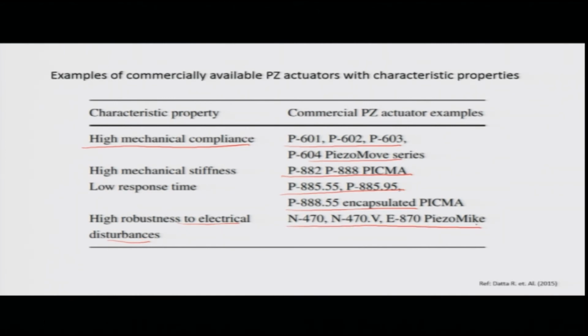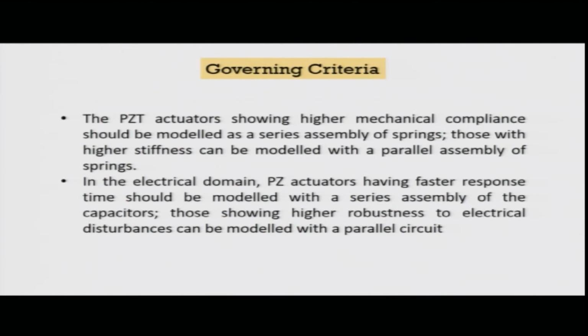So, from the characteristics of the commercial actuators, you would know what is built into these multi-layer stacks. So, what are the governing criteria for us? The piezoelectric actuators which show higher mechanical compliance should be modeled as a series assembly of springs. Those with higher stiffness can be modeled as a parallel assembly of springs. This point we have to keep in our mind.